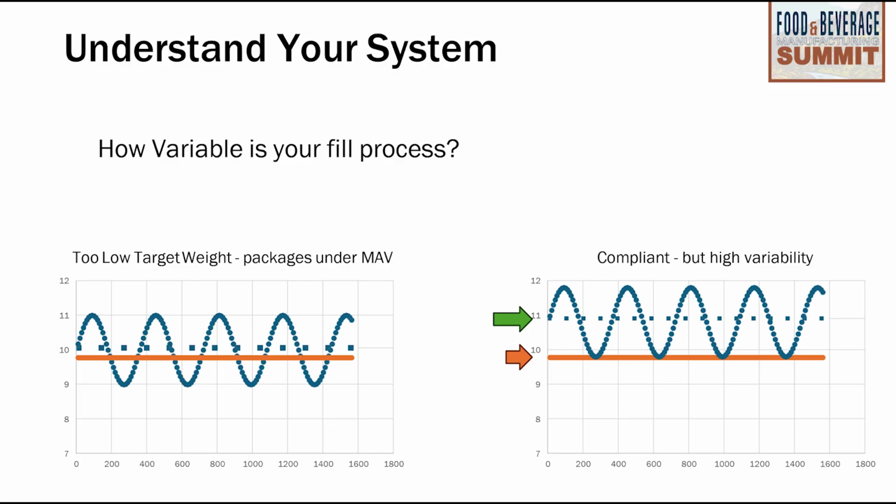In automated monitoring systems, these are usually done with an in-motion checkweigher. Be sure to use the correct tare weight and, as before, recheck it frequently. These systems will detect any underweight package. They also count all the packages filled. You still must routinely verify the accuracy of this system, and the lot average must still be verified. All newer checkweigher machines offer easy monitoring and calculations and reports.